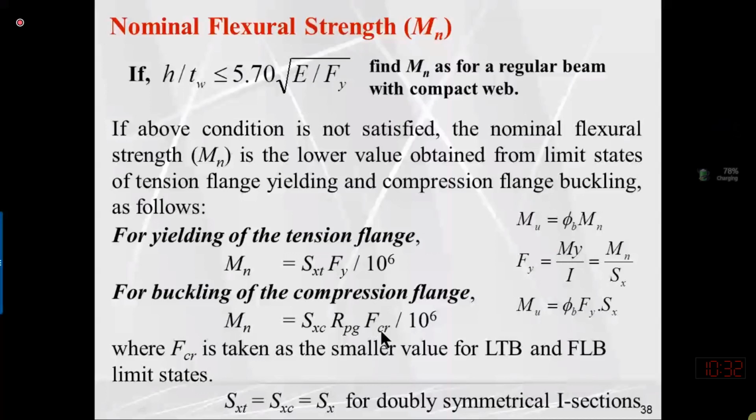One, with reference to lateral torsion buckling. Lateral torsion buckling means that this is the stress value at which the member will start twisting in the lateral direction, which is a function of the unbraced length that we determine in beam design. The other thing I told you in the start is that our flanges may be compact or non-compact.